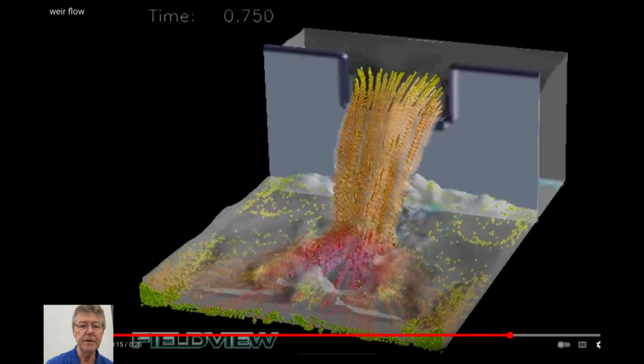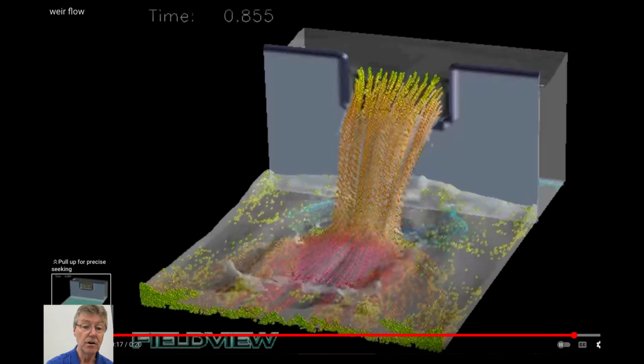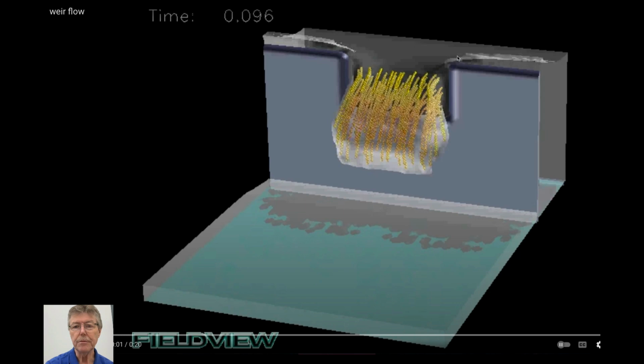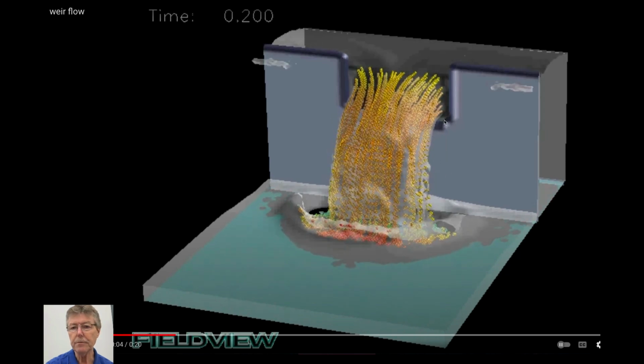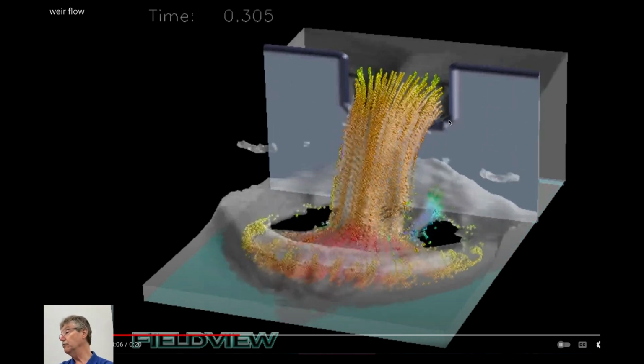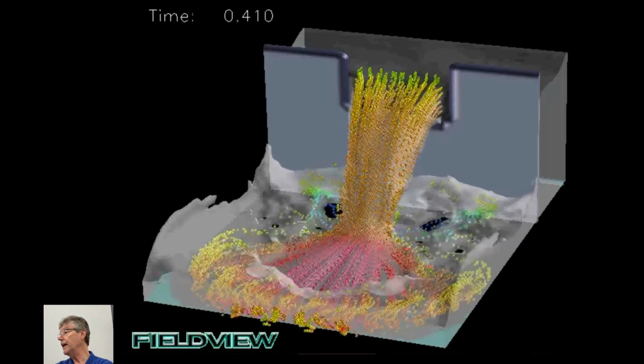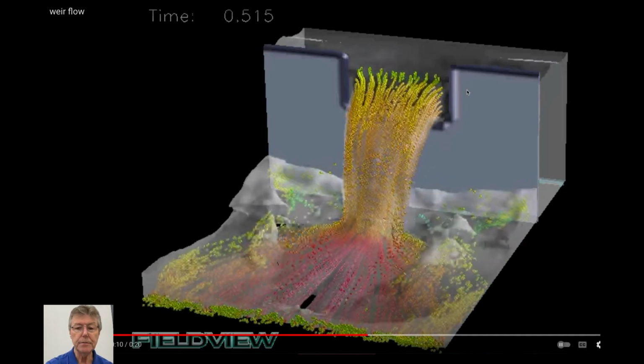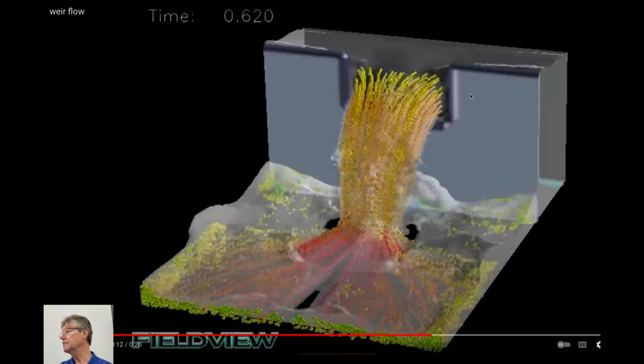And maybe either from the upstream and downstream elevations, or depending on the situation, from the upstream elevation relative to the bottom of this board, you can use essentially the equation of a free jet that we've already talked about to be able to figure out exactly what the flow rate is.